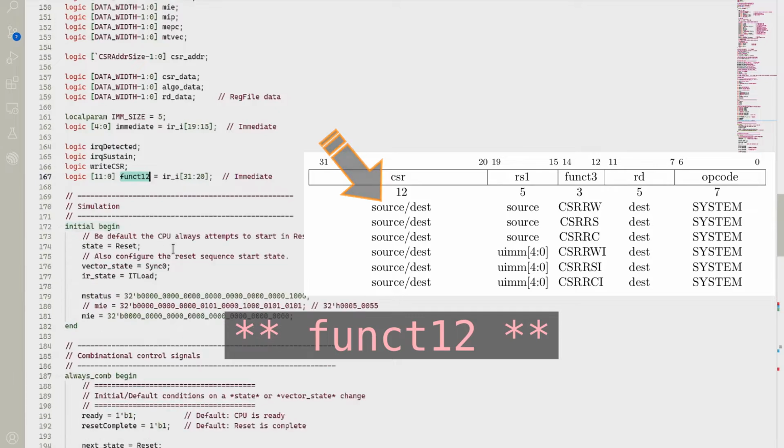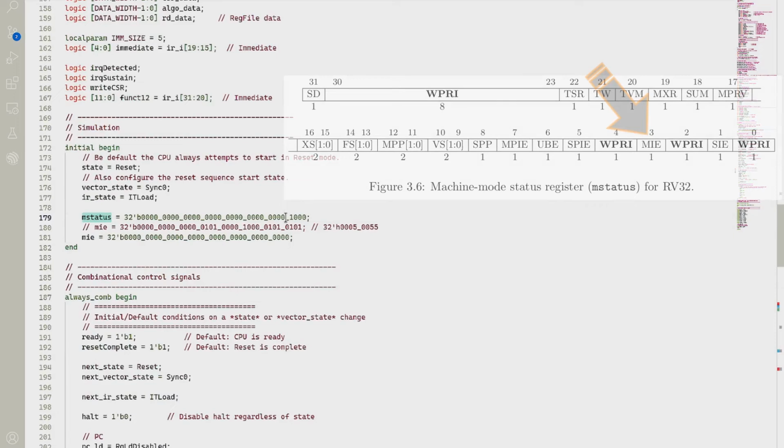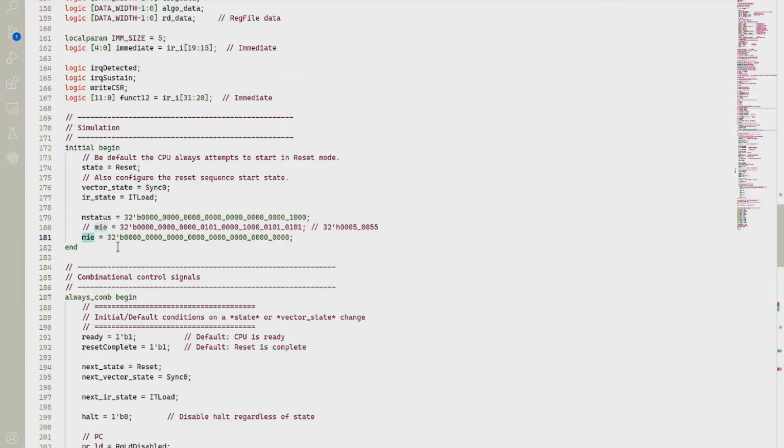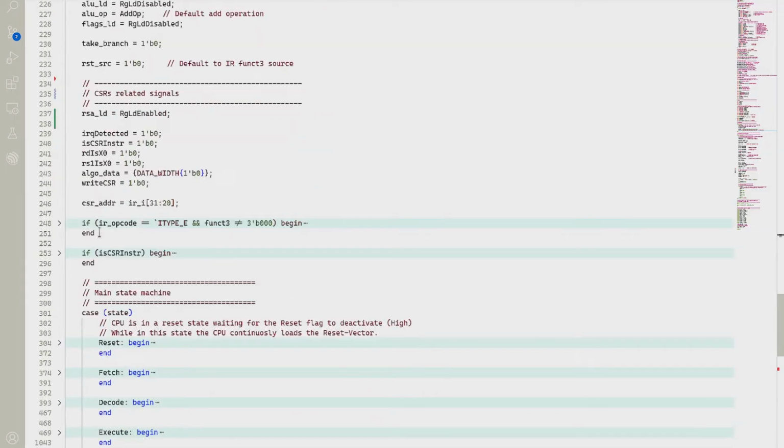We've also added a couple of initialization sequences for the M status register. We might want to start off with global bits enabled and maybe have some sort of enablement bits set up in IE. In this case, we're looking at different types of values, so we can test whether we're clearing and setting instructions. And if we come down here, we'll now see a whole new section. It's relatively large, that contains everything necessary to set up default values for this.